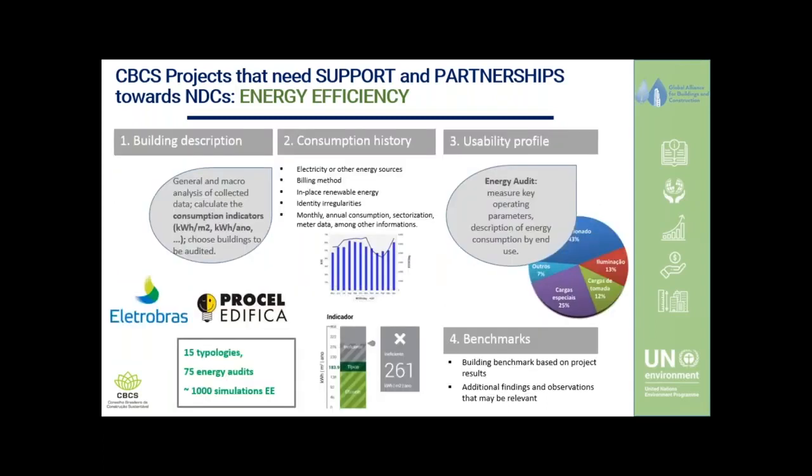Next slide, please. And here we will show you a little bit more about this project with the Eletrobras, our National Agency of Energy. We are working with 15 typologies because we want to benchmark all of these 15. We are going to do 75 energy audits and more than 1,000 simulations in energy efficiency to understand the behavior of these buildings and construct the benchmark equations to have the levels on our label.